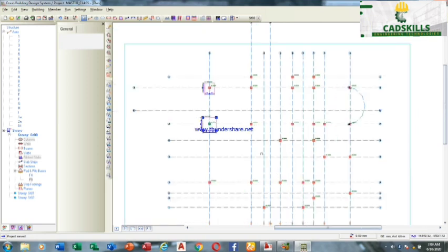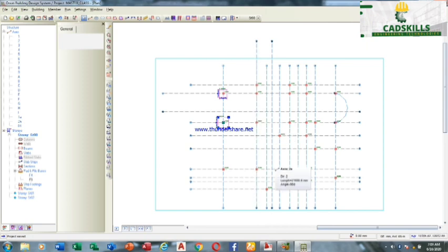But you can see that the inner columns are suffering. They are the ones bearing the load, not even these outside, not the edge ones. They are the ones suffering inside. Can you see it now? So if you go and carry a 300 column and put here, and carry a 150 column and put here, it means that you don't understand structural design.